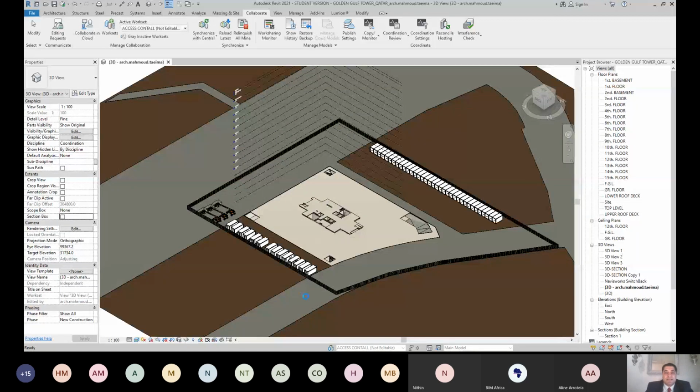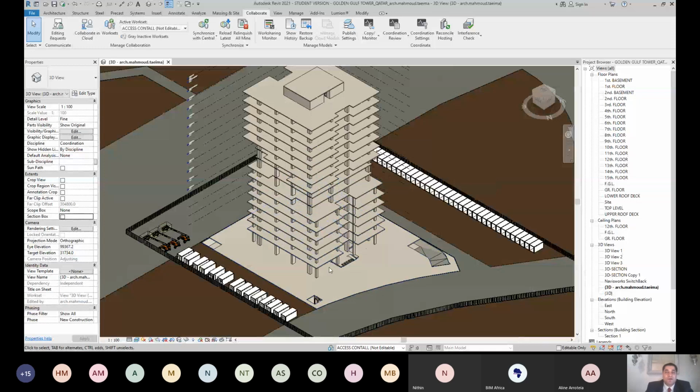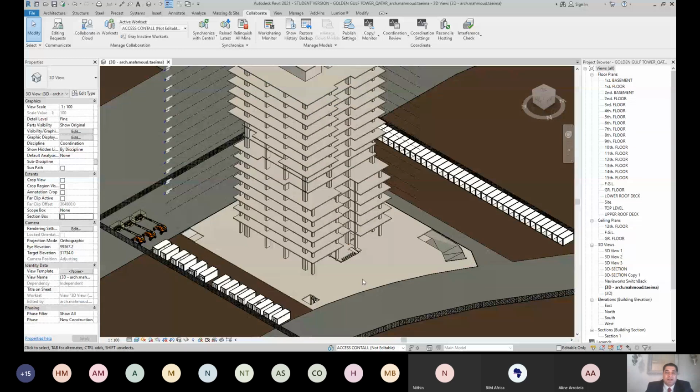This is the whole building structure now, for all floors, foundation, underground floor level and upper ground floor level. All quantities we can calculate from Revit and build our schedule to get the original duration for every item, what the start time is and what the end time of the work is.